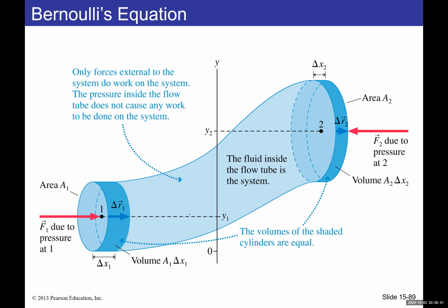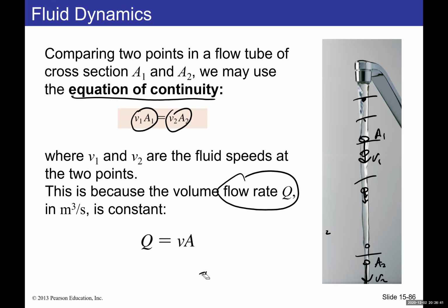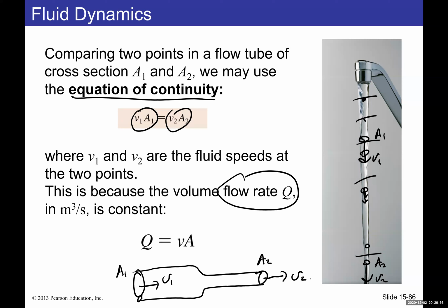Continuing with another principle, another equation, this is known as Bernoulli's equation. By the way, if I go back here, this equation works as the continuity equation. Let's say you have a tube that goes like this and changes the opening like that. For example, this is A1, this is V1, this is A2, and this is V2. The flow rate is the same, that means A1 V1 equals A2 V2. So if I'm looking at V2, it's basically A2 over A1 times V1, rearranging for V2.